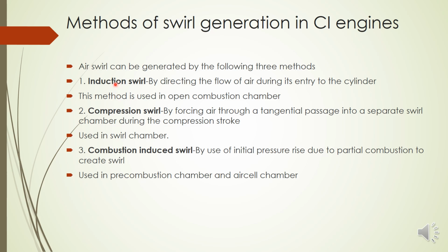In the first one, we are generating swirl in the suction stroke itself, that is during the entry of air in the cylinder. In the second one, it is generated during the combustion stroke. Third one, it is generated by the partial combustion of the air fuel mixture. So that is how we will classify the swirl generation.